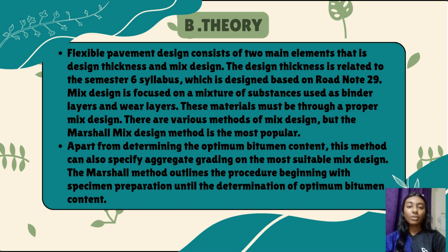Secondly, the theory of this test: flexible pavement design consists of two main elements, that is design thickness and mix design. The design thickness is related to the semester 6 syllabus, which is designed based on Road Note 29. Mix design is focused on the mixture of substances used as binder layers and wear layers. These materials must go through a proper mix design.